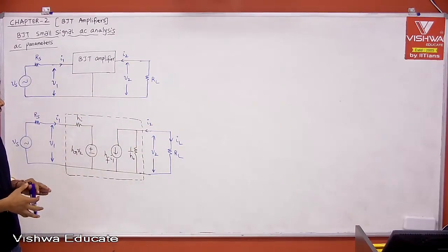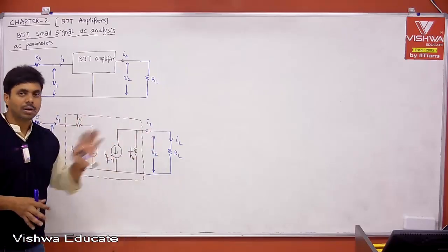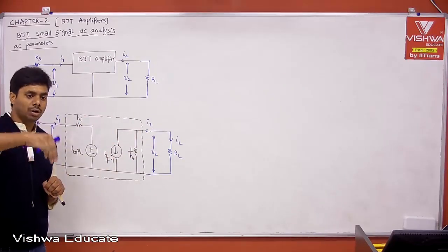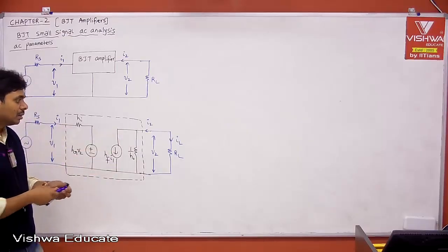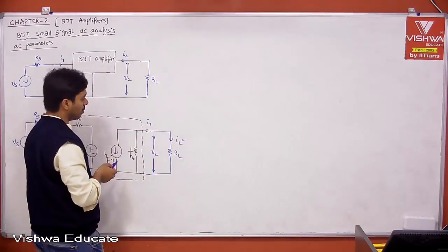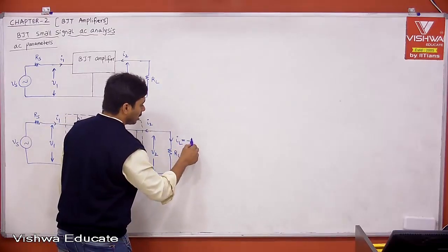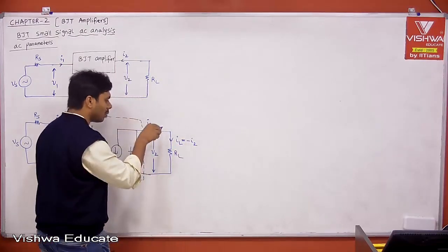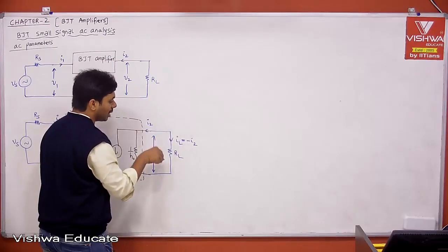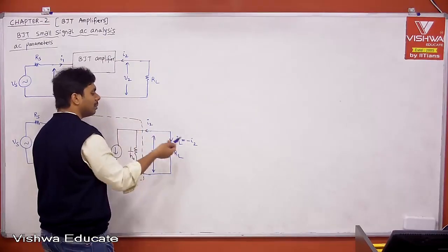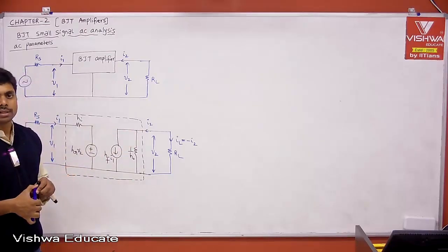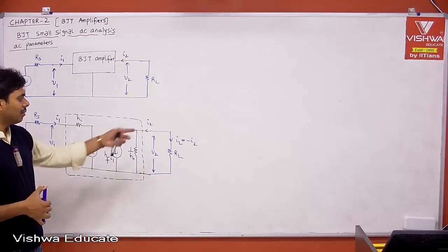If I speak with respect to source and load, how much current the amplifier pumps into the load is IL. With respect to the two-port network model, that is opposite. If the real current flows in the direction of interest it will be positive; if it flows into the amplifier it will be negative, because the direction is taken care of by the sign.